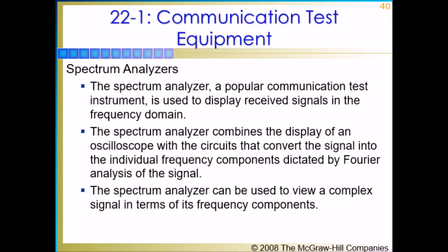The four basic techniques of spectrum analysis are bank of filters, swept filter, swept spectrum superheterodyne, and fast Fourier transform. All these methods do the same thing: decompose the input signal to its individual sine wave frequency components. Both analog and digital methods are used to implement each type. The most widely used are superheterodyne and fast Fourier transform.